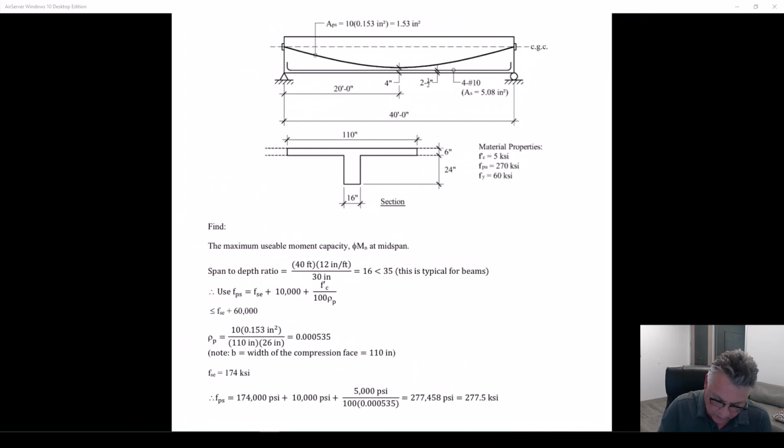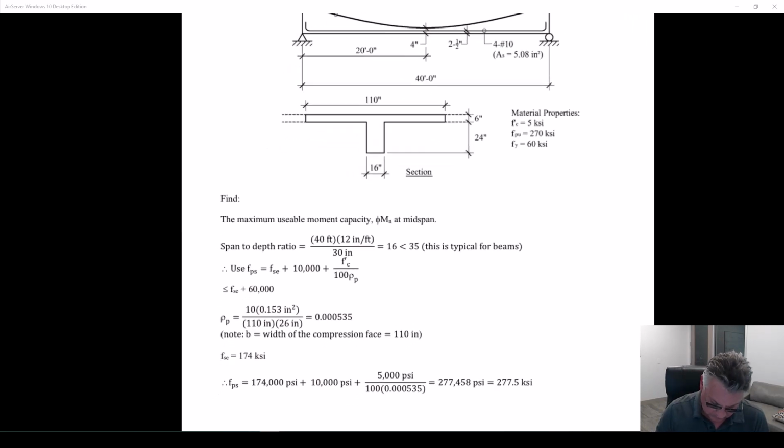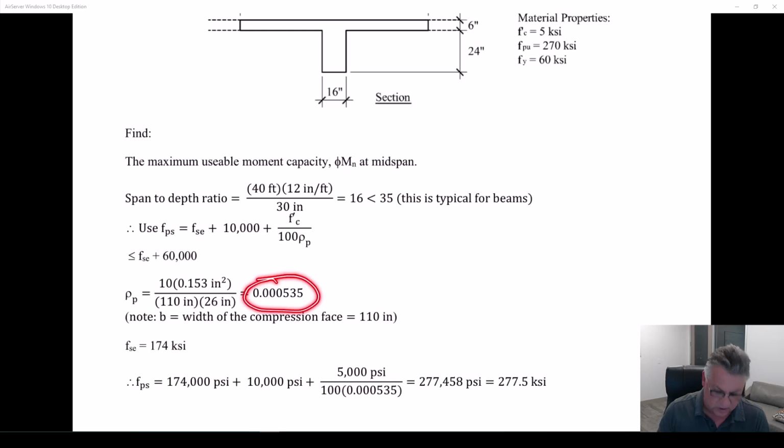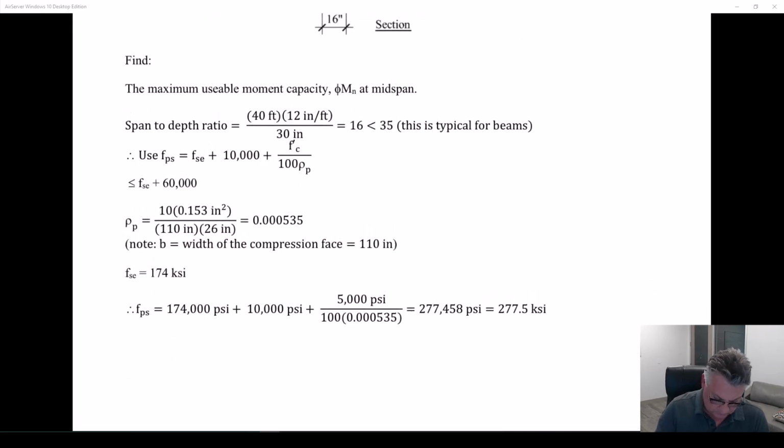So we have tension on the bottom of this beam, and compression on the top of this beam, up here. So always know, wherever you are, whatever you're doing, where compression is and where tension is. So rho changes dramatically in this case, and that changes that equation substantially. Remember, all we did was change this from a rectangular section to a T-section.